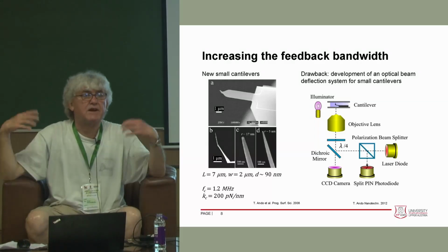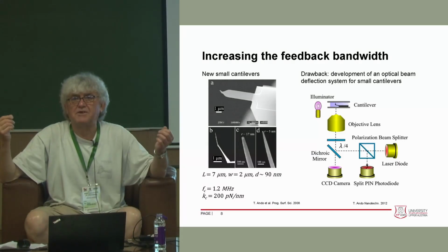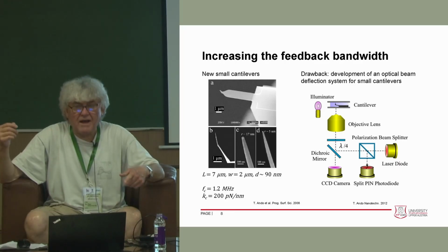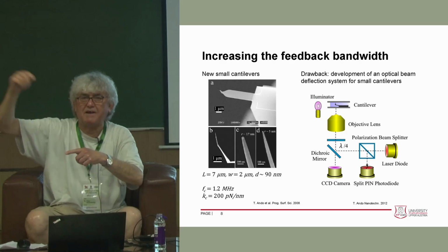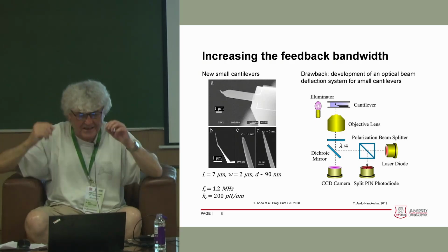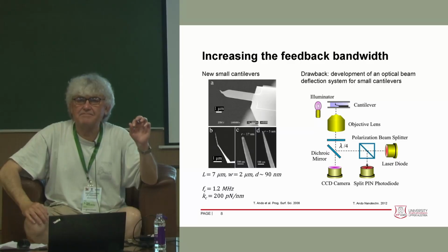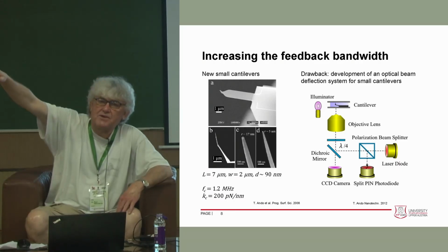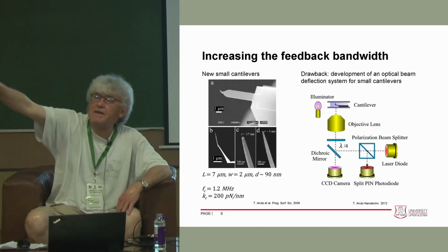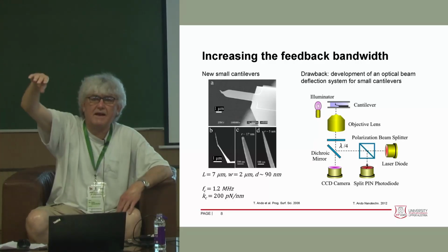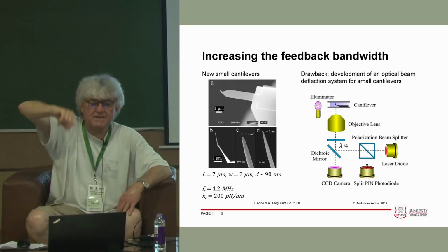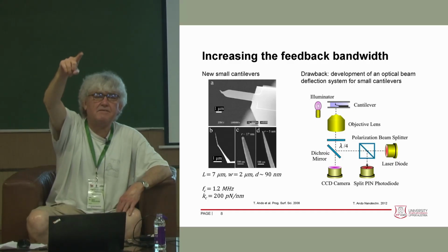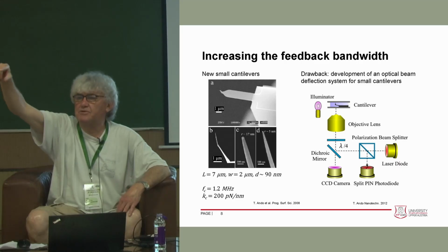So that was the other challenge, to improve the optical detection system. And to come now from the 50 milliseconds to the 5 milliseconds, maybe also just shortly tell it, is that with even shorter cantilevers, that are being produced with 2 to 3 micrometers, that is one thing. And then the other thing is to scan only into one direction, record only into one direction, and then fastly go back. And then an additional kind of parachuting system, which is also embedded, because if you scan fast, the feedback has difficulties to follow.